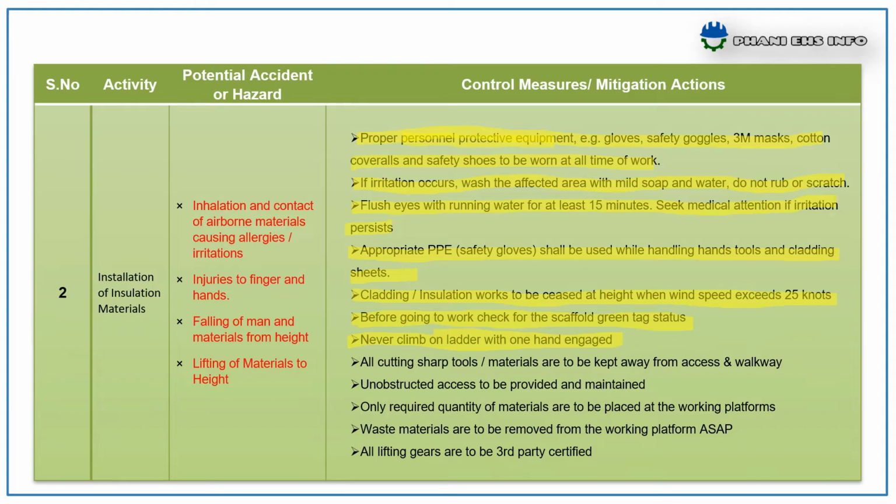All cutting sharp tools or materials to be kept away from access and walkway. Unobstructed access to be provided and maintained. Only required quantity of materials are to be placed at the working platform. Waste materials are to be removed from the working platform as soon as possible, and all lifting gears are to be third party certified.